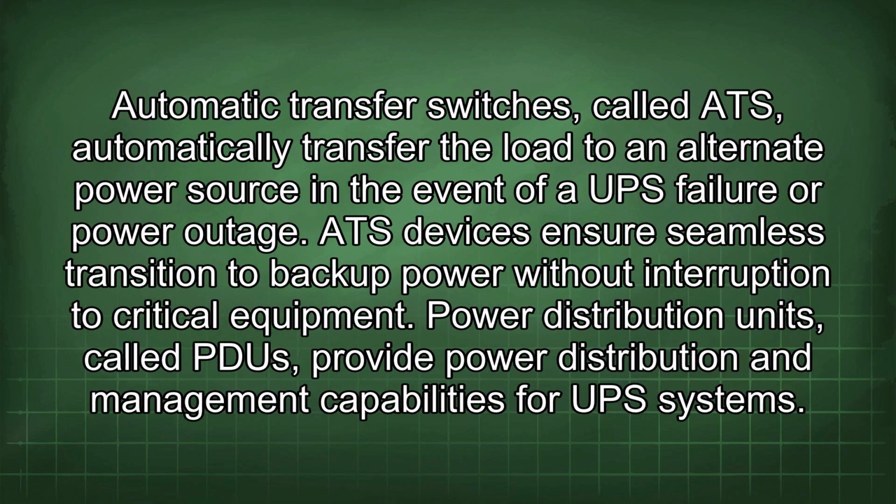Automatic transfer switches, called ATS, automatically transfer the load to an alternate power source in the event of a UPS failure or power outage. ATS devices ensure seamless transition to backup power without interruption to critical equipment.